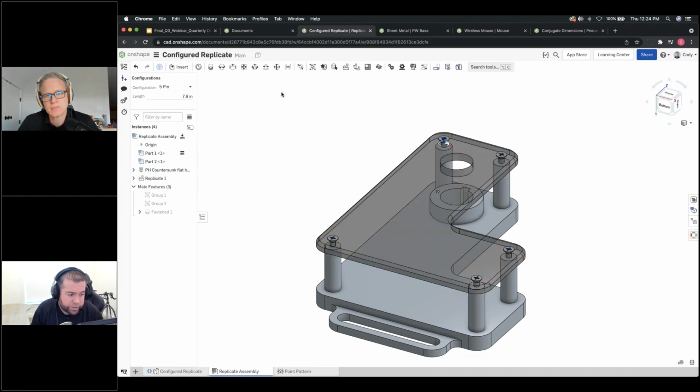What's different is how it looks and behaves. So in this case, we have the countersunk head flat screw, right? We have replicate for each of the instances, and that's really what's unique about this. This is now an item in the instance list of the assembly, and it's a real feature rather than just being a true replication of all the geometry associated with it. And the power of this is in how it regenerates. So if the underlying features, the underlying faces that drive them change, this will update parametrically.